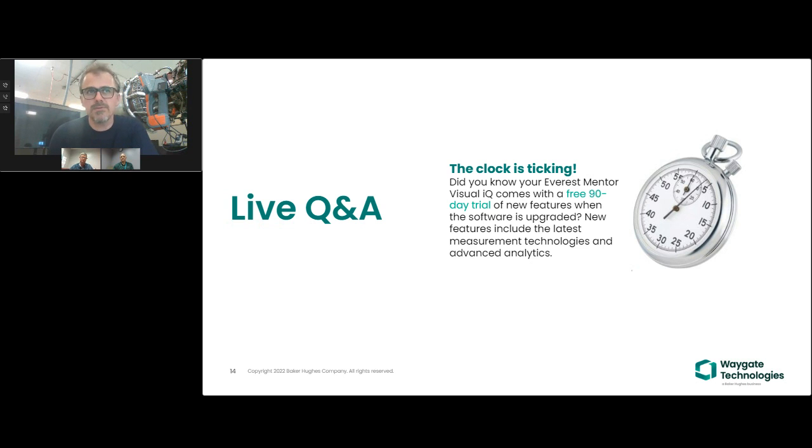If you don't have access to additional diameter probes, for instance, you're fixed with your 6.1 millimeter option, which I can understand, are you using the right tip? Have you got a near focus tip fitted? Do you have access to the far focus tip, or even the orange and blue ultra bright tip, in order to transmit more light into that cavity? So choice of probe diameter and choice of tip are the hardware rules that you'll need to apply.